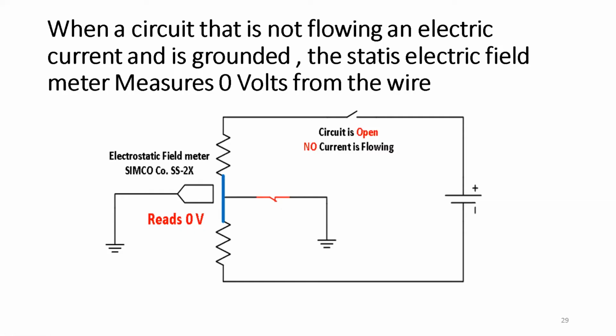We have a simple electrostatic field meter, not a reciprocating type, because a reciprocating type is always taking a sample of the electric field and then testing it against a reference. And that does screw up electric field measurements. With a simple one, which is just really a FET that's driving a meter on a battery, you can see these kinds of electric field changes better, but they're much harder to use because they like to drift.